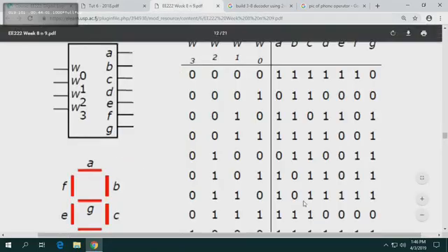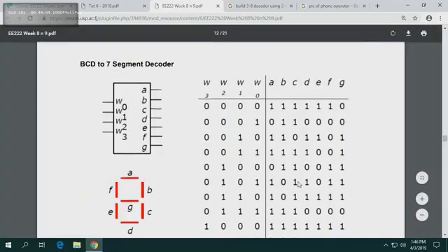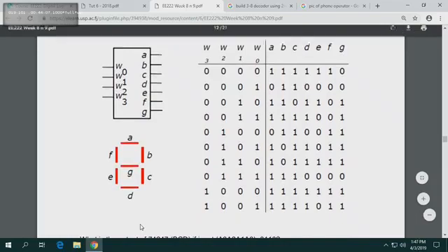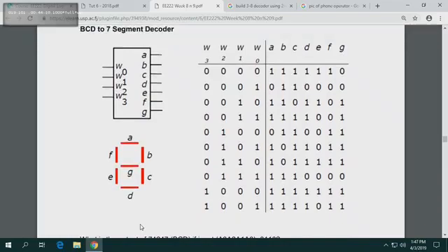So eventually we will end up with this truth table. Can you see this truth table? That's your truth table. So this is your binary combination, all your binary combinations. Input side is always easy to populate. You just do the standard combination input. And output side, you have to look. So A, B, C, D, E, F, right? So 0, remember I said we did this, G will be 0, right? Okay, now, how many outputs in this chip? That's the chip which we drew. How many outputs? 7 outputs. Therefore, how many Karnaugh maps will you be doing? 7 Karnaugh maps.